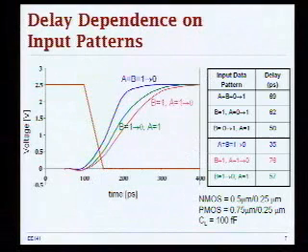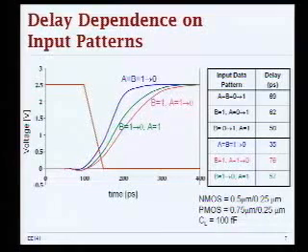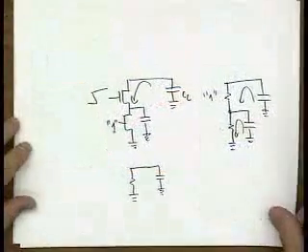Good. So now the question obviously becomes, well, this is really getting out of hand. This is ugly. I mean, this is just a NAND gate. How about more complex gates, like 3-input, 4-input gates, different logic functions, topologies? It's going to be really difficult. So let's now try to understand a little bit what we can do with our gates to make propagation delay about balanced in the worst case.